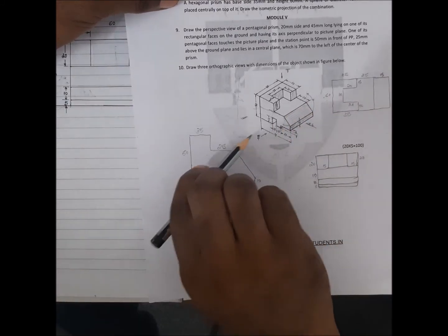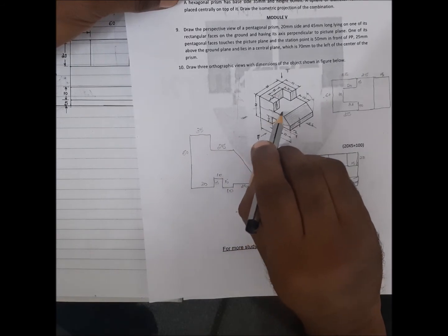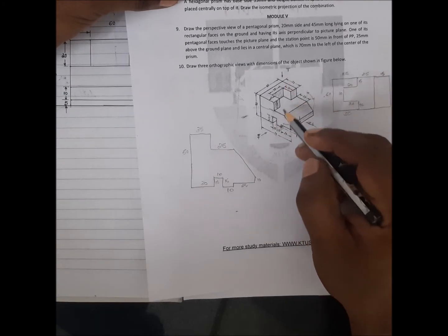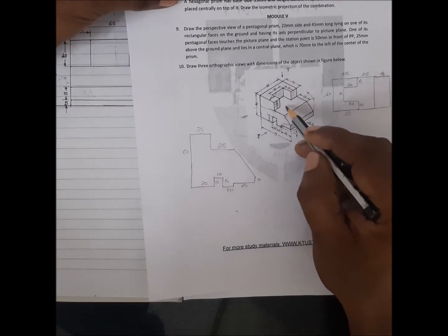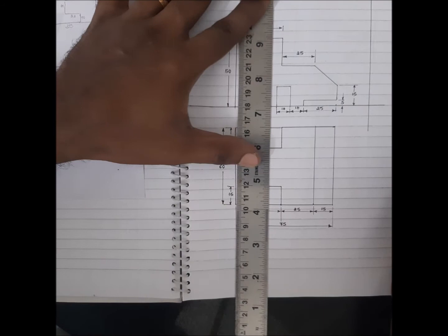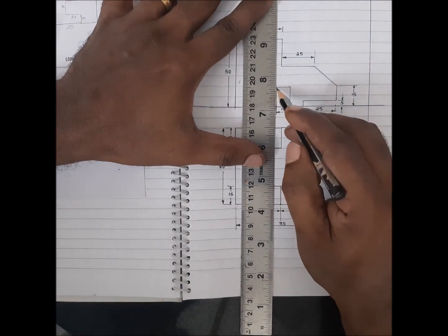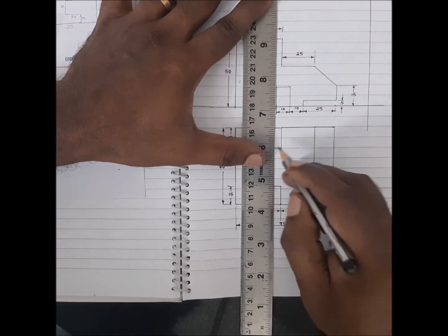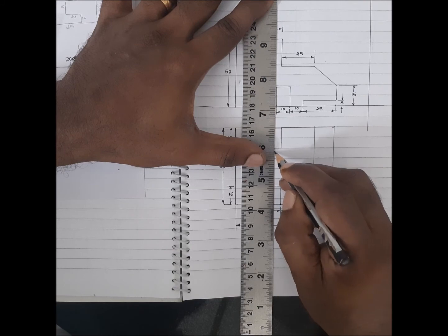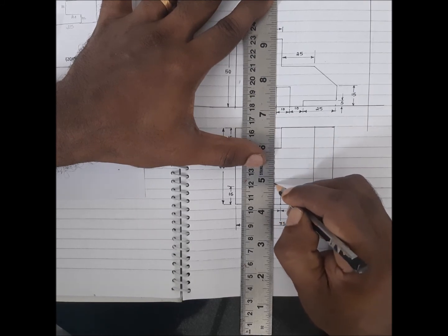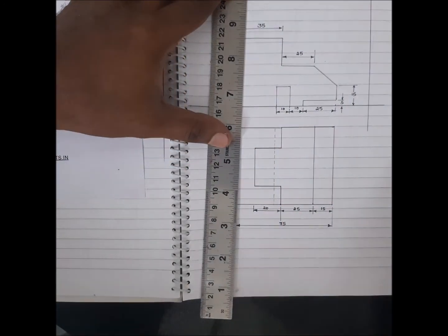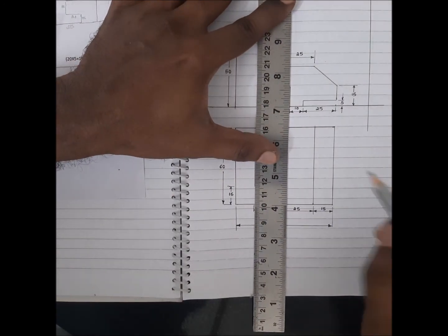When you look from here you see a pocket, and the edges of the pocket go all along. So when you look from the top, you won't see these edges because of the surface here, but you have to show this edge as a hidden one. After making the drawing, you identify that, and this is the hidden edge that you see in the top view. So it goes all the way along. Okay, so that's what I'm doing, it goes all the way. And this one also, no exception.